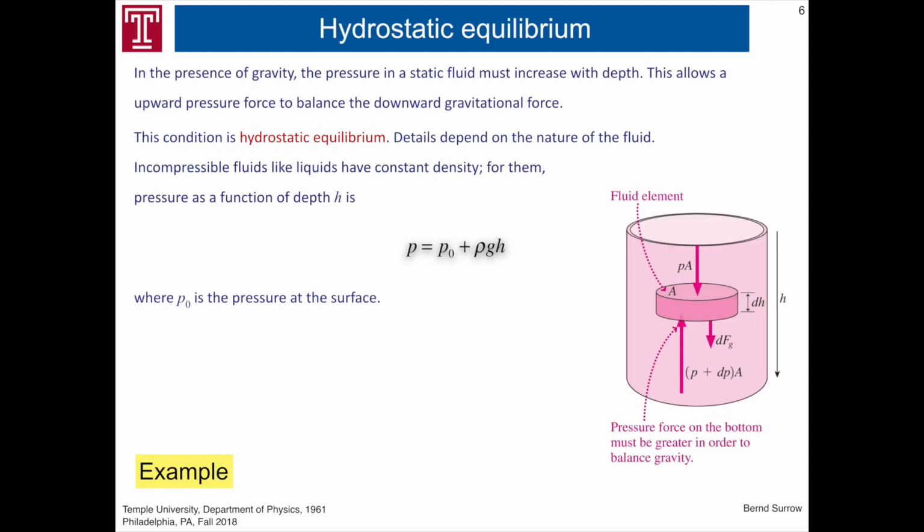Now, in the presence of gravity, the pressure in a static fluid must increase with depth. This allows the upward pressure force to balance the downward gravitational force. This condition is called hydrostatic equilibrium. Details depend on the nature of the fluid. Incompressible fluids like a liquid have a constant density. For them, the pressure as a function of depth is